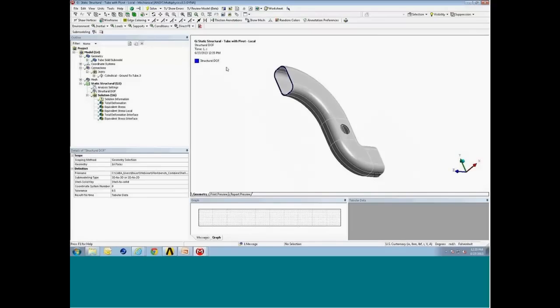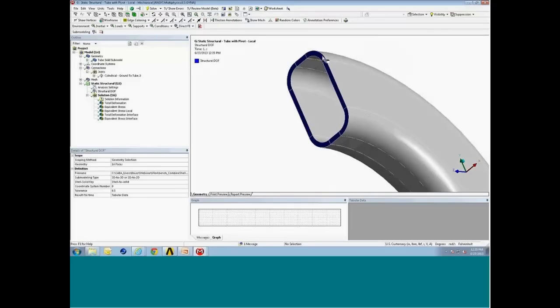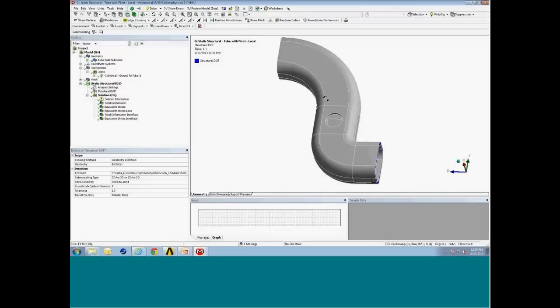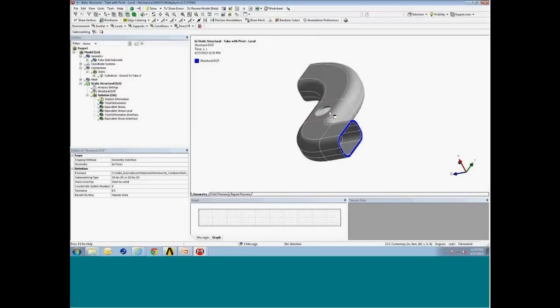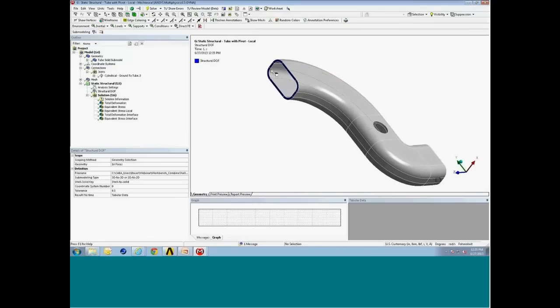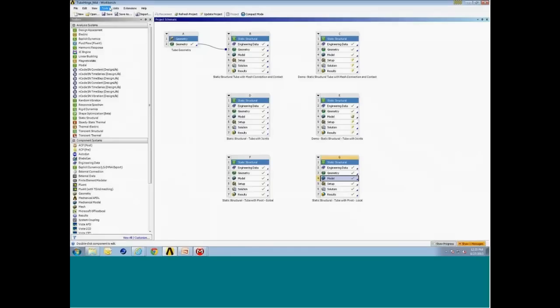Essentially, let's select the surfaces of the solid as a method of cutting, transferring the shell degrees of freedom over to our solid. So I've got that on both sides of my submodel. Those shell translations and rotations will get transferred across through translation degrees of freedom on my solid model. You merely specify the file name here. In this case, since I was building the global model in Workbench, I specified the RST file name throughout in the file structure. Take a look here.